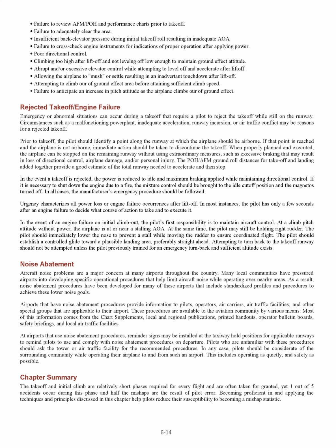abrupt and/or excessive elevator control while attempting to level off and accelerate after liftoff, allowing the airplane to mush or settle resulting in an inadvertent touchdown after liftoff, attempting to climb out of ground effect area before attaining sufficient climb speed, failure to anticipate an increase in pitch attitude as the airplane climbs out of ground effect, rejected takeoff/engine failure.